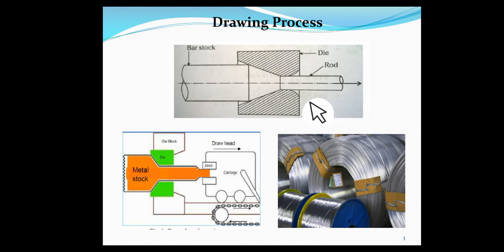So now come to the operation. When the entry portion of the workpiece material is gripped by using the external equipment and the pulling force is applied, the workpiece will be moving through the dies continuously due to the indirect compressive stresses and also the tensile forces. The force will be applied on the workpiece material. Due to those forces, the reduction or deformation takes place. Remember, reduction in cross section of the workpiece takes place by using tensile force and also the indirect compressive stresses.